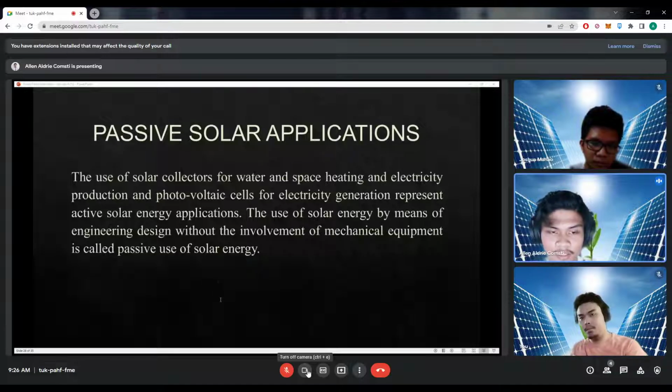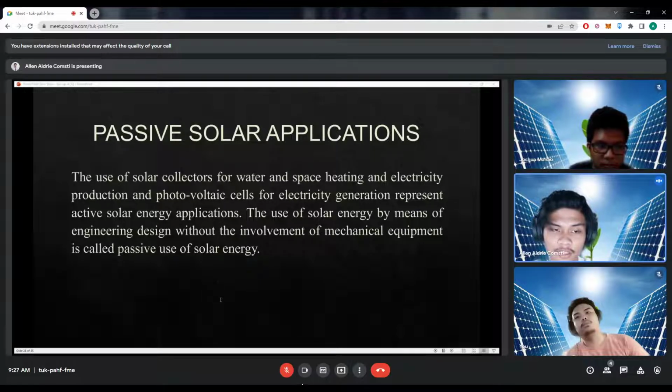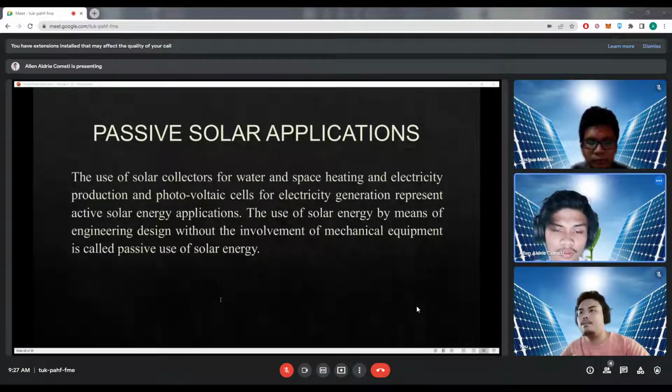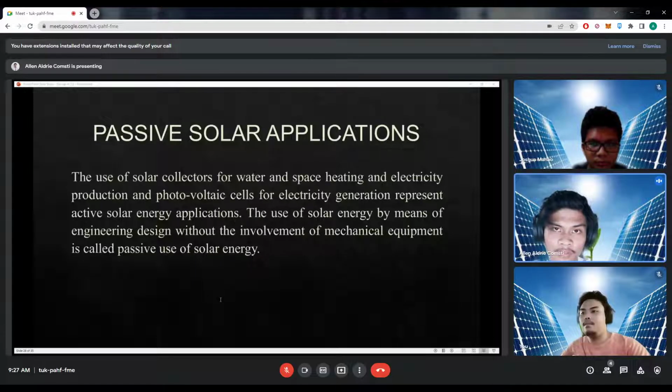Significant energy savings can be accomplished if a house is designed and built to receive maximum solar heat in winter to minimize heating energy consumption, and minimum solar heat gain in summer to minimize cooling energy consumption. This may include correct selection of orientation of walls and windows, size and type of windows, wall materials, and surface color and finishing of wall surfaces.